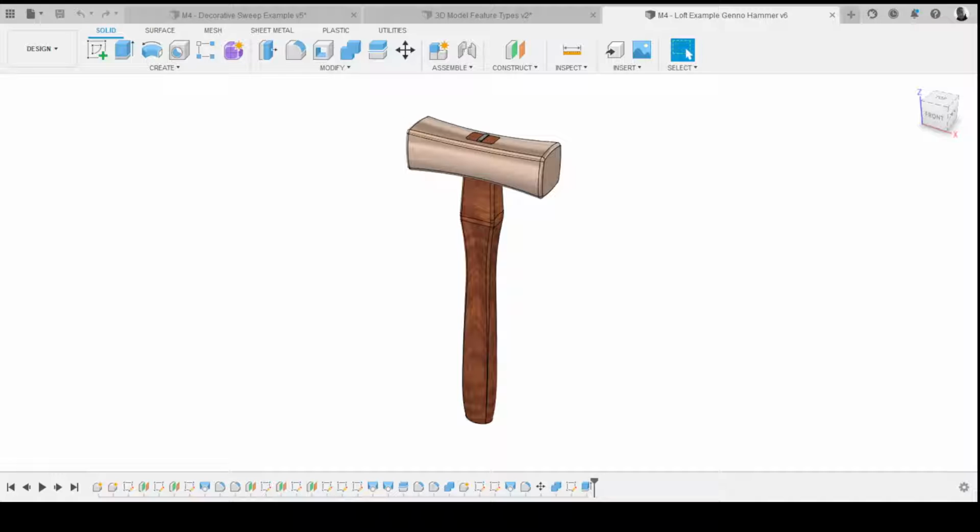Is it an extrusion? Is it a revolve? Is it a sweep? Or is it a combination of those things all put together? And if it's not one of those things, your only other option really is to use the loft function. So, for instance, something like this, what kind of modeling function is that? Could be an extrude, could also be a revolve, pretty straightforward. This one here? Any ideas? A revolve. So it's quite easy to start analysing shapes and try and get them to fit those classic modelling types.